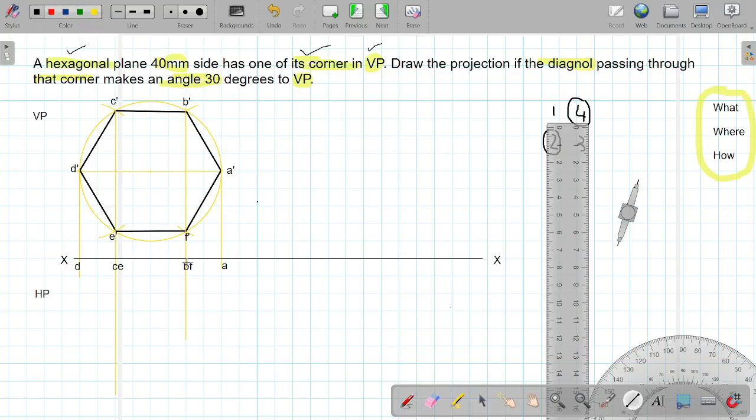Now to complete step 2, you have to make this line dark, starting from point A to point D. This is the step where students forget to make this line dark and the marks are reduced. So from A to D, because this entire plane will be visible as a line in the top view, this entire thing will be dark. So this completes step 1 and step 2.